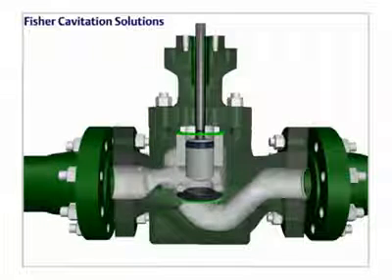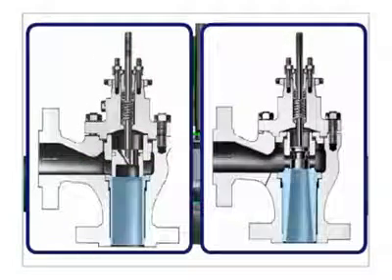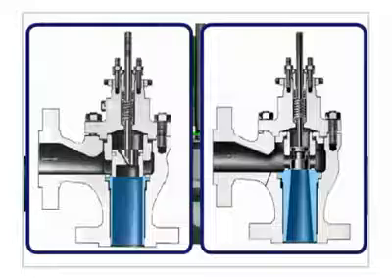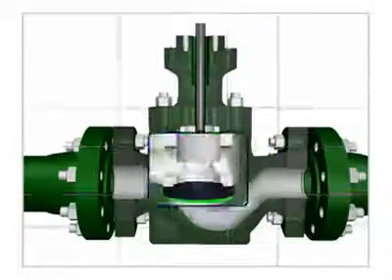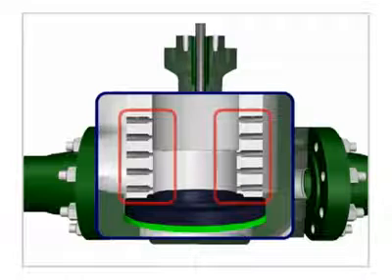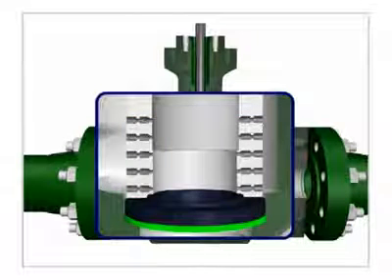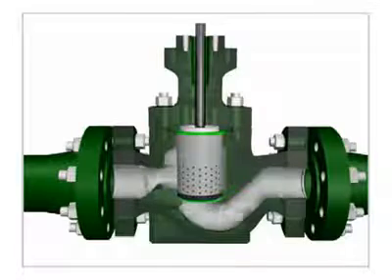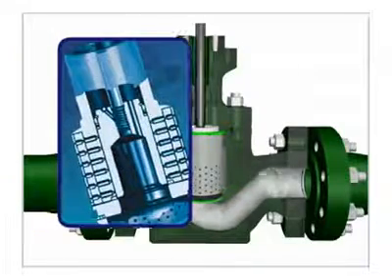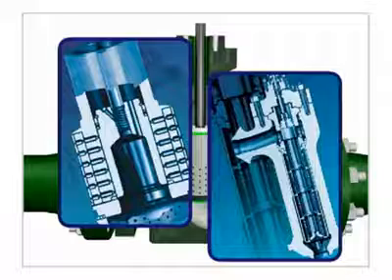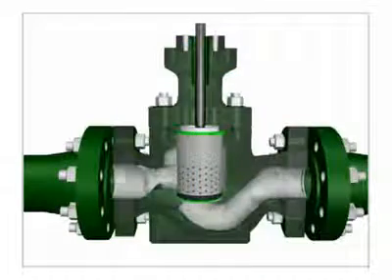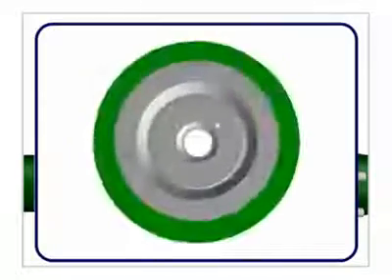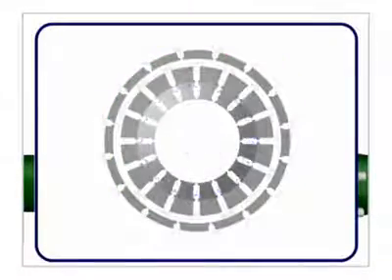Emerson offers these solutions. Valve liners are constructed of hardened materials to protect the valve body. Pressure staging keeps the pressure from falling to near a liquid's vapor pressure, which helps prevent vapor bubbles from forming. Pressure drops are staged by the use of expanding nozzles or expanding flow areas. For example, in the Cavitrol 3 valve trim, nozzles have holes shaped to manage flow separation.